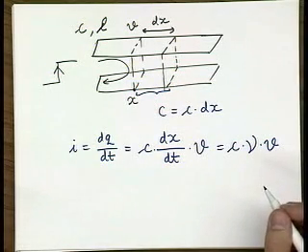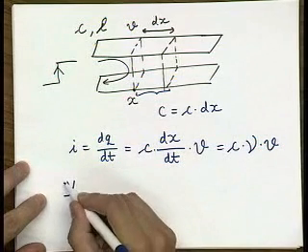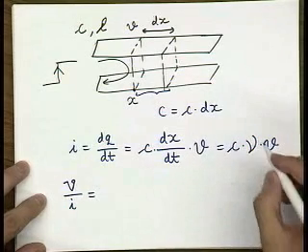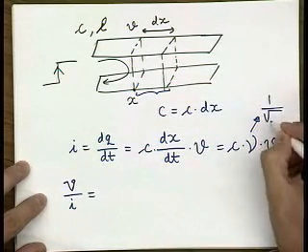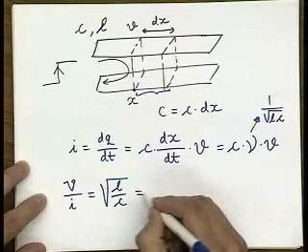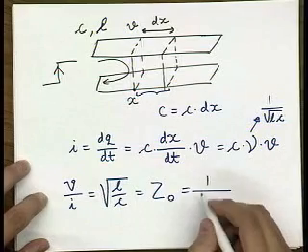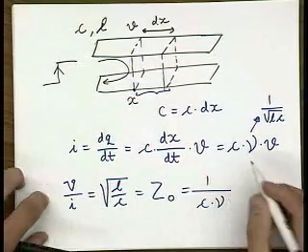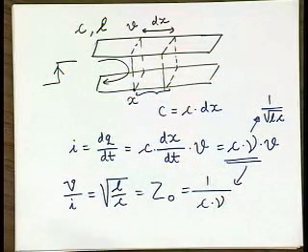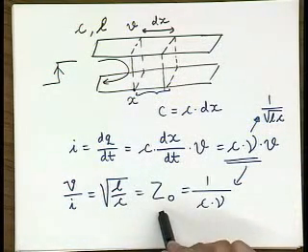So now what's really interesting from this analysis, if you take V divided by I, and you know that this speed is equal to 1 over the square root of LC, you get impedance, and that is also equal to 1 over C times the speed over here. So what's really interesting is that a signal sees the remainder of the wire as a constant impedance.